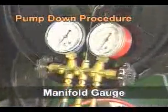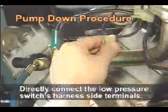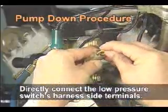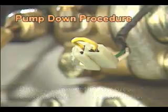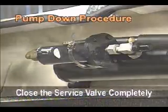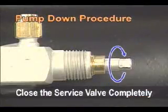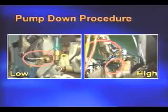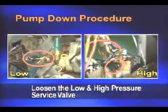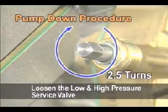Install the manifold gauge. Remove the low pressure switch connector and directly connect the low pressure switch's harness side terminals. Close the service valve at the receiver outlet completely. Loosen the low and high pressure service valve by turning the valve stem 2.5 turns clockwise.